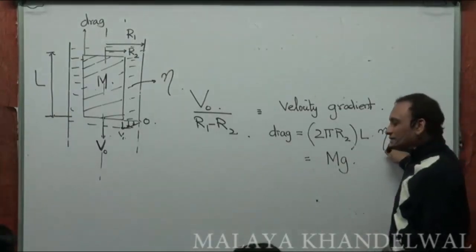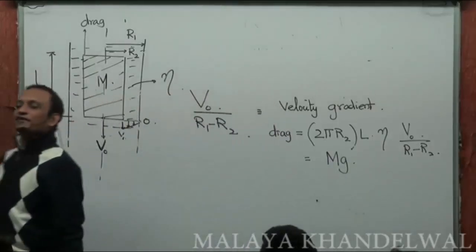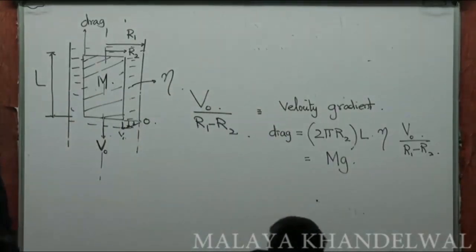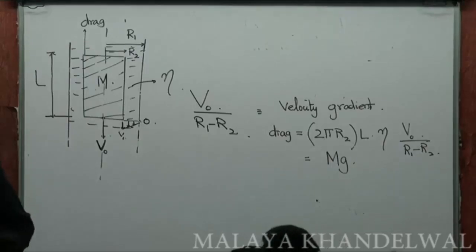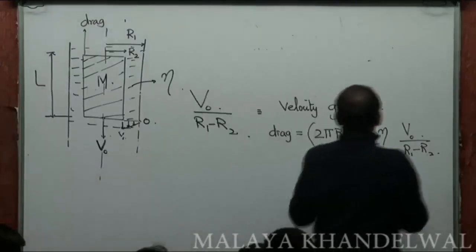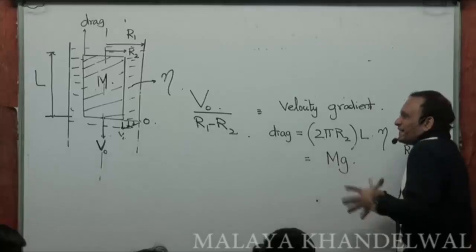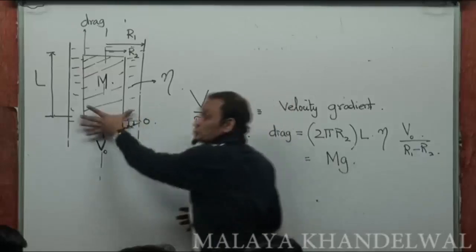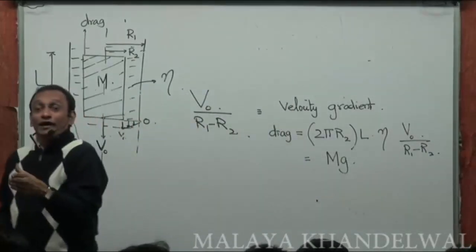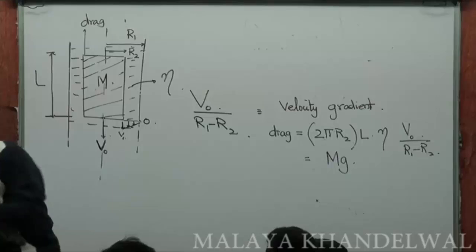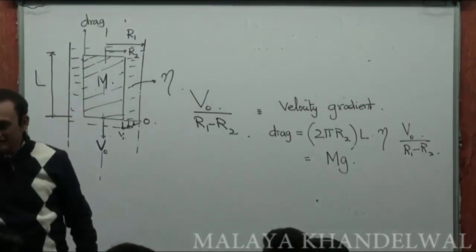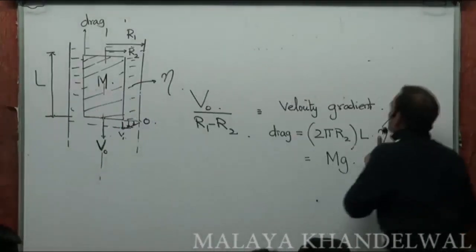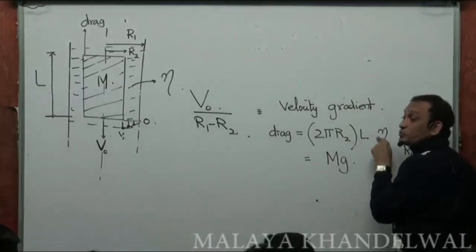Now, one thing, it's a far-fetched thing. You may not have exactly that liquid of that value of eta, right? So when they are carrying out designs of cylinder piston arrangements in which the piston moves inside the cylinder, they can prima facie start with, these are all designs on paper to begin with, right? They know that they have to work around certain ranges of R1 and R2 which are allowed, right? They can change the geometry of the piston cylinder arrangement, but they can't force nature to produce a liquid of a certain viscosity, isn't it?